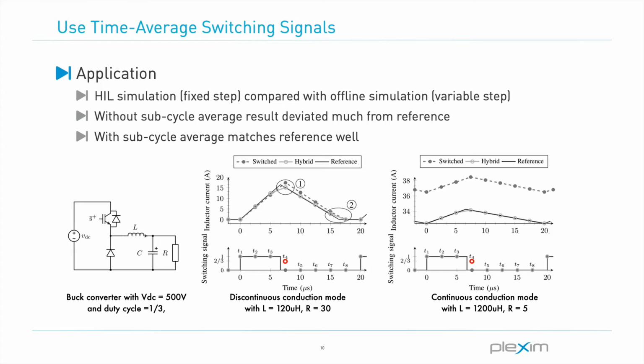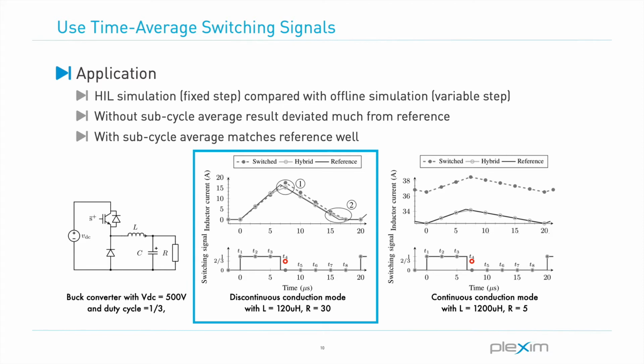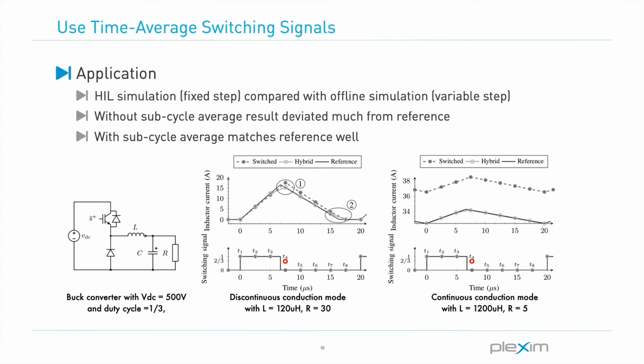The last problem that I mentioned initially, the natural commutation of current, can be seen in the plot in the middle. Here the diode turns off in the interval of T7 to T8, but one can neither guarantee that the simulation step coincides with a turn-off transition, nor actually calculate the time of the switching instant without knowing the external circuitry. This becomes especially a problem in DC-DC converter topologies, where the current commutates on a time base given by the switching frequency and not, for example, a slower mains frequency.